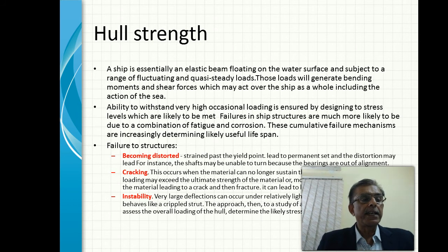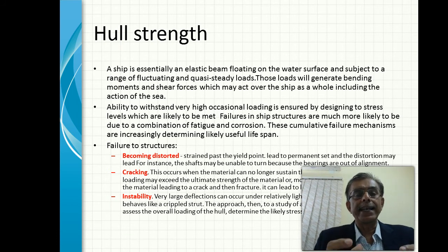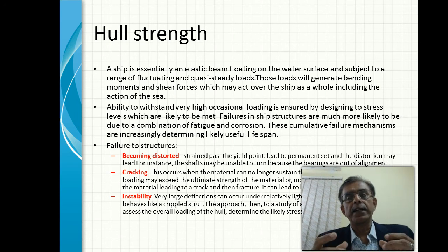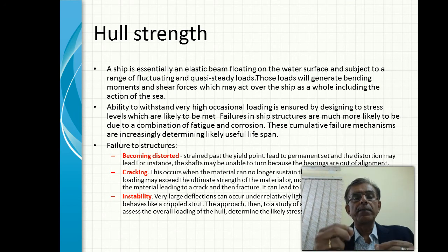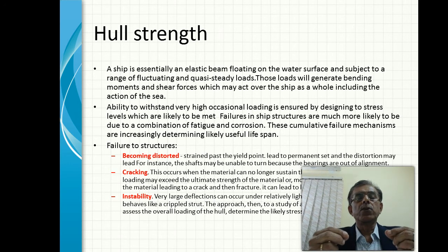A crack is related to a failure, but a crack can come not only due to a load being exceeded, but also due to fatigue of the material. Because the ship is in a seaway, the loading is alternating all the time, so fatigue can set in.